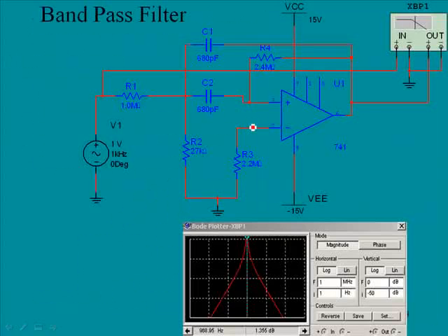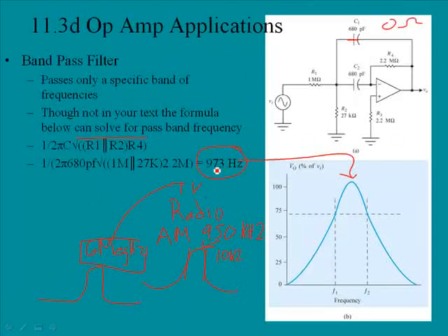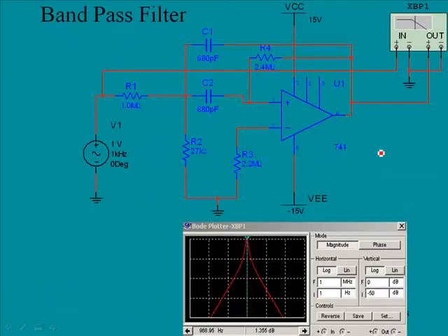Now, I built a circuit in Electronics Workbench. This is in fact that circuit. This was not in your package of circuits, but I just wanted to confirm the fact that this actually is the frequency. And you'll note here is our signal source. Here is the capacitor going to the input, and then here is the capacitor that's in the feedback loop. And you'll note here is the Bode plot, and the blue line here is capturing the point of the passing of the frequency.